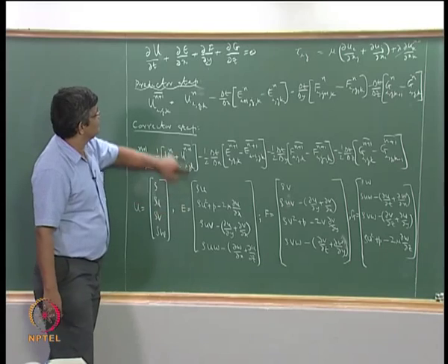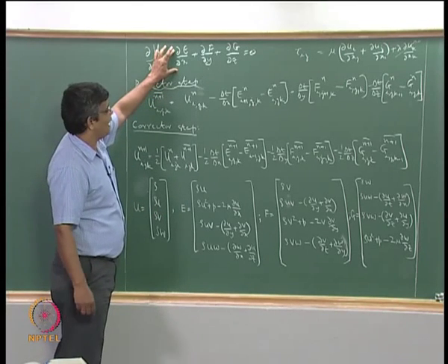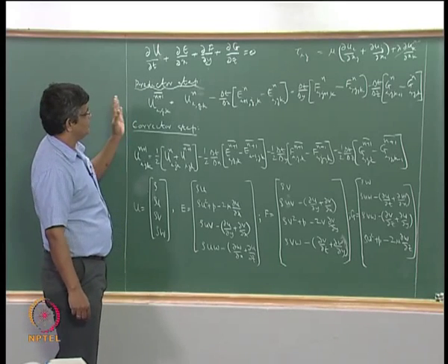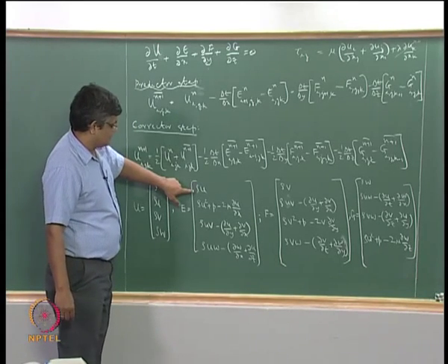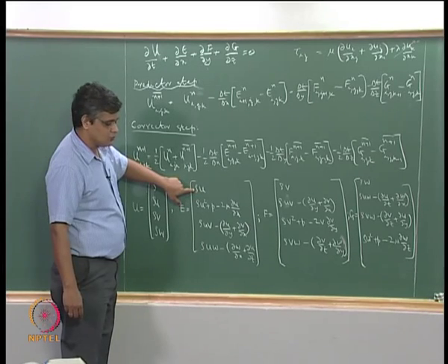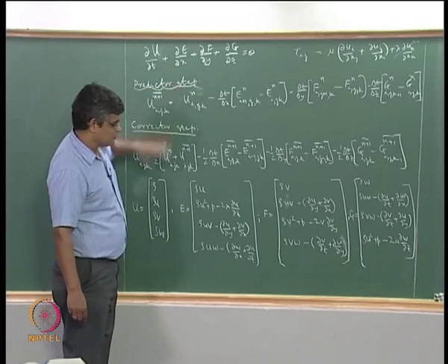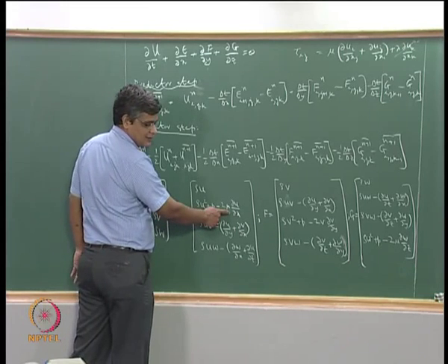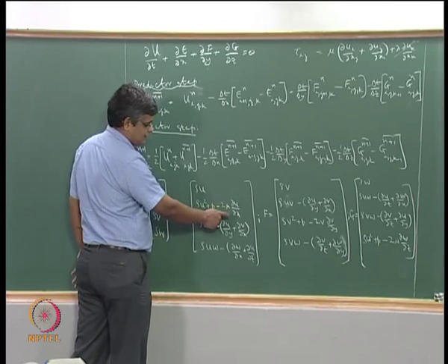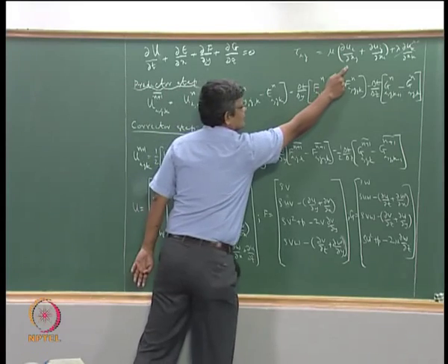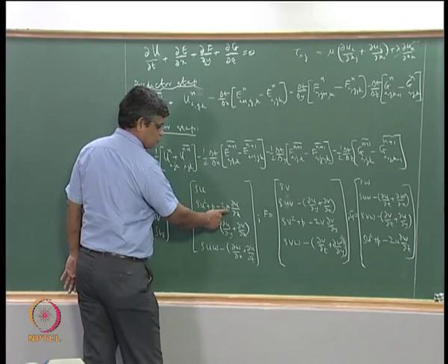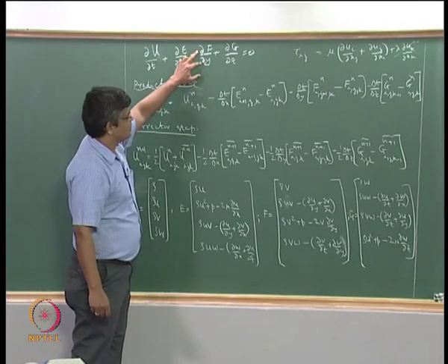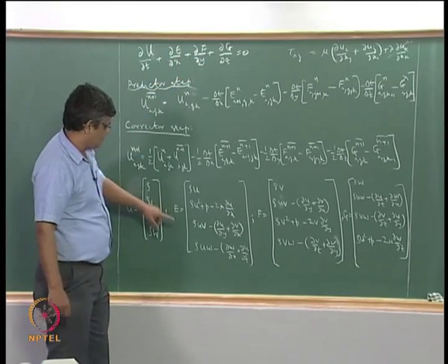Now the E term, which represents the advection component coming from the x faces, the positive x face and negative x face, has, in the continuity equation, rho u, in the x momentum equation we have rho u square plus pressure and the shear stress, that is minus tau xx, which as per this is evaluated as minus 2 mu dou u by dou x,